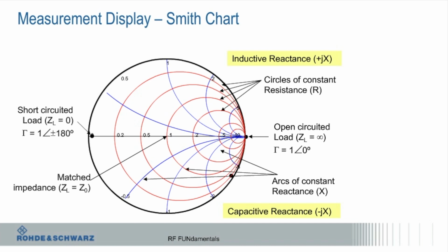If I measure a point here, then I want that to get to here, 50 ohms. So it'll tell you first off what that point is, but when you add delay to it, you can look and measure what this impedance is.